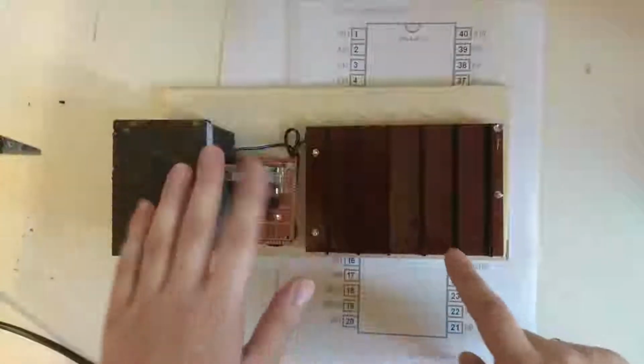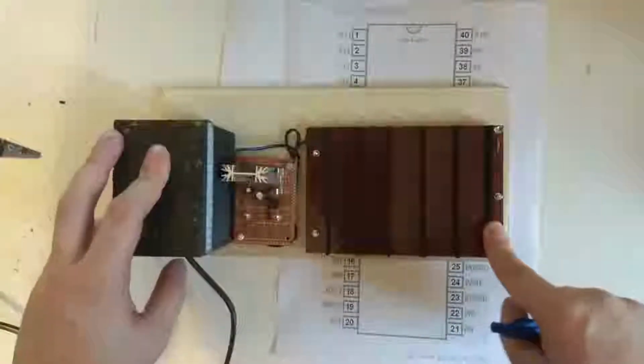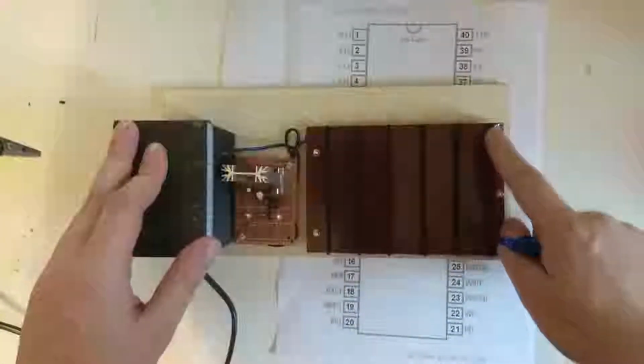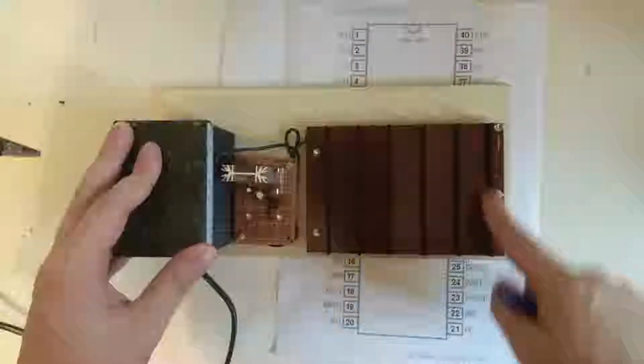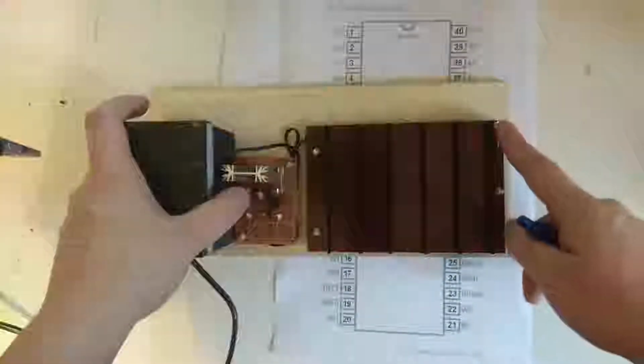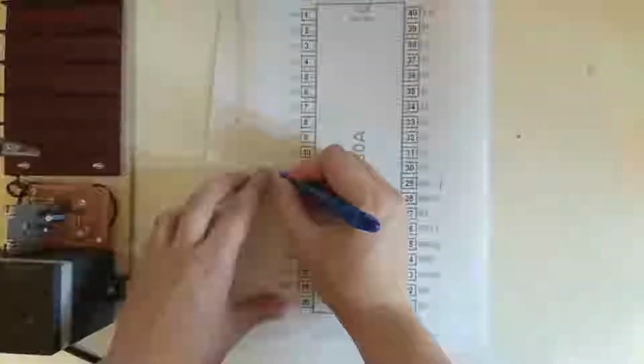With the backplane and the power supply all done, it's time we actually go into the building a computer part. And to do this, we first have to decide what signal we want to have where on our backplane. Because of the way I designed this, one thing is already determined, and that is ground is line 1 and VCC over here is line 2. And now I can basically decide what we want to do.